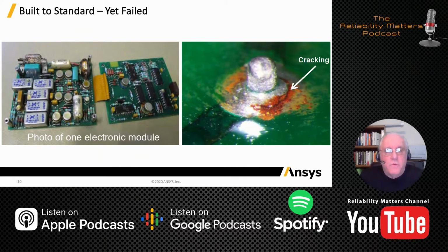And that was the situation with this particular rudder limit control piece of avionics, that there was an intermittent that was caused by this cracking solder joint on the relay. And this had been rejected and tested several times. It was taken off the aircraft, sent into the avionics shop. It passed, so NTF, let's put it back into service again. So the particular accident that resulted from this, there were multiple causes. There was a lot of weather disturbances going on in the Pacific Ocean at the time.